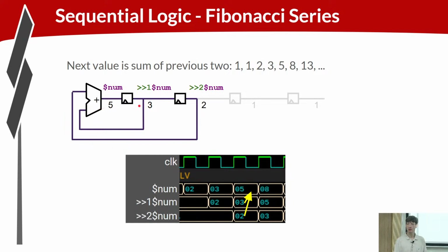Anybody notice anything missing? Yeah, we need to reset this. We just talked about the fact that every sequential circuit needs to be reset to a known state. Known state for this circuit, we can reset this to have the previous number and the previous number be 1. That'll initialize us, start us off.